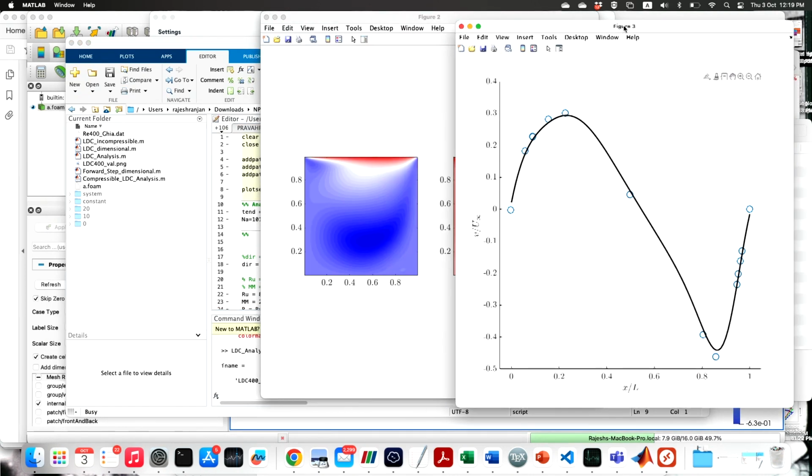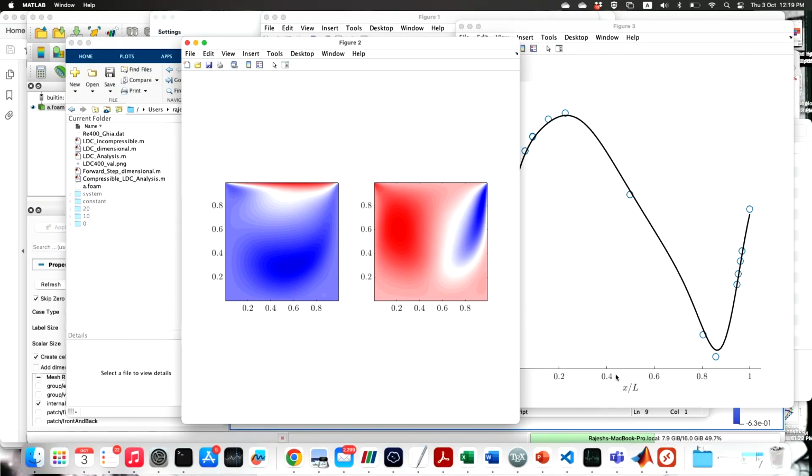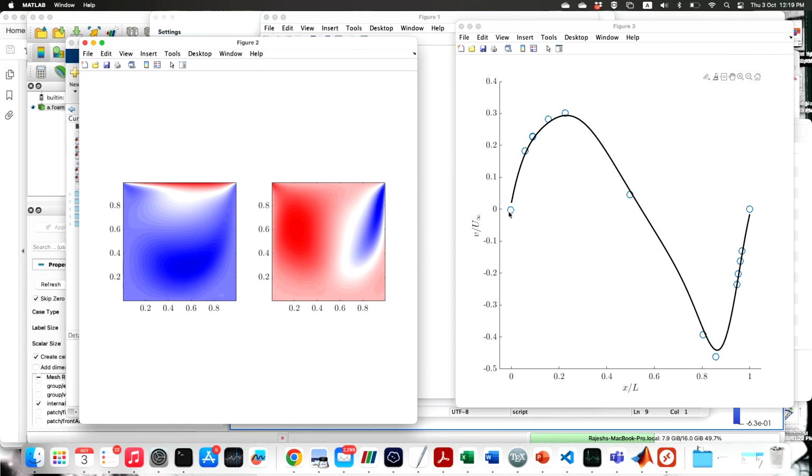Okay. So now you can see here the same thing I am plotting using MATLAB, but you can use Python or any other tool. Typically I advise all the students that if you want to analyze a flow, get the data in a format that you understand. Of course, Tecplot and ParaView or Nsight, these tools are there to help you visualize the flow, but if you want to quantitatively see how the flow is looking, qualitatively you can easily see using ParaView. Even quantitatively you can see, but it will require some effort, but if you understand the data you can manipulate it the way you want.